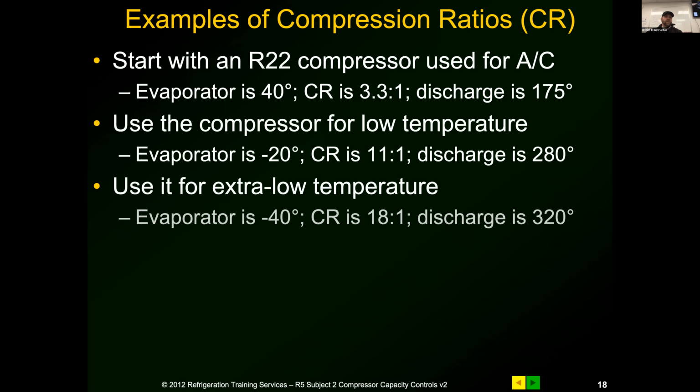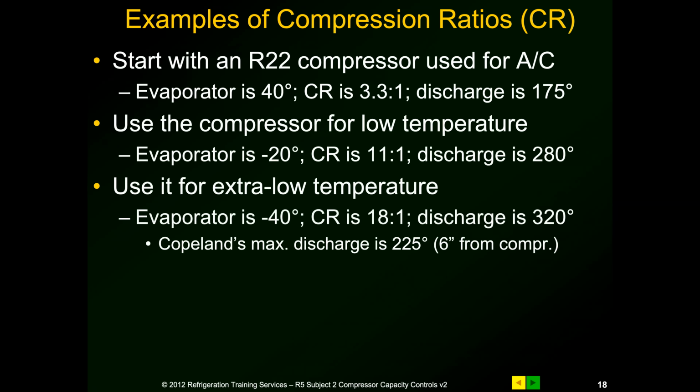So if you use it for extra low, the evaporator is at negative 40 degrees. Now we're at 18 to 1. Your discharge is 320 degrees. At that point, we're cooking oil. Okay. Copeland's max discharge. Go ahead. That's when you also need your head coolers. Yep.